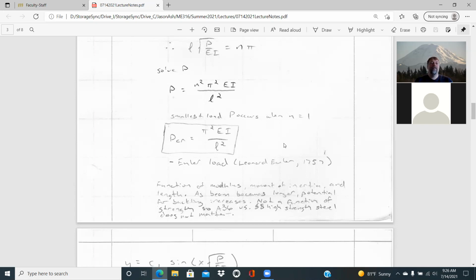And that change in microstructure can have a significant impact on the strength of that material. But one thing it doesn't affect really as you go through that heat treatment process is the Young's modulus. That stays fairly consistent through those heat treatment processes. It's just the strength that is affected.